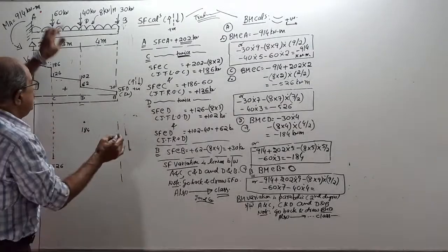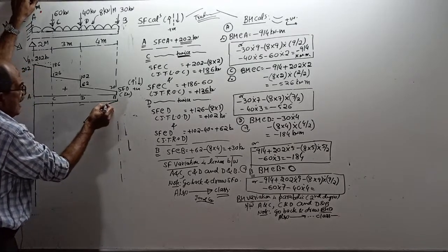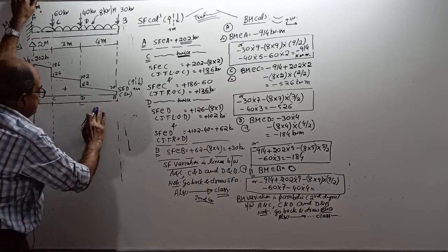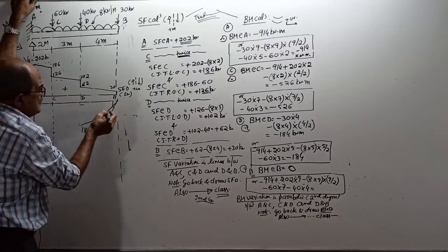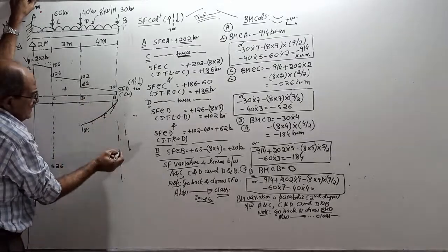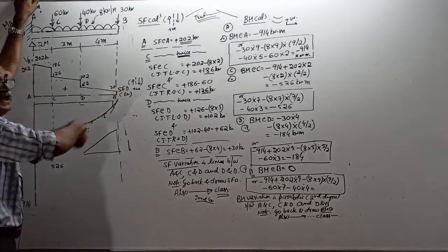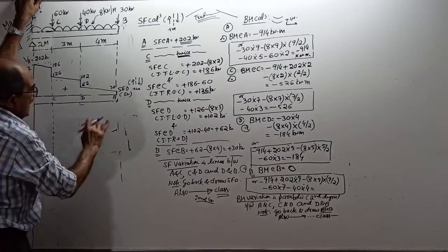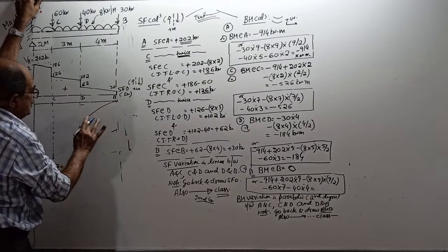Increase. See, if I draw curve this way, see now, here slope is lesser. As you come here, slope becomes more, slope increases. Correct. But by chance, if I draw this way, see here, here slope is maximum. As you come here, slope reduces. That is correct if shear force diagram is what? If the shear force is decreasing. But shear force increasing means slope should increase. So correct diagram is like this. Now clear or not?